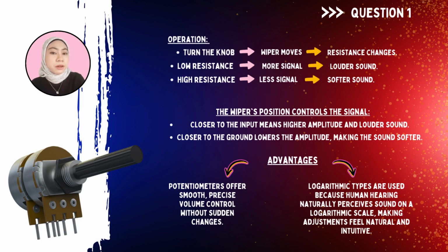Lastly, about the advantage, the potentiometer offers smooth, precise volume control without sudden changes. Logarithmic types are used because human hearing naturally perceives sound on a logarithmic scale, making adjustment feel natural and intuitive.